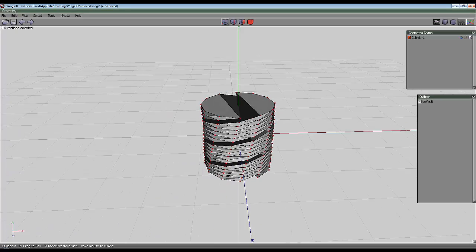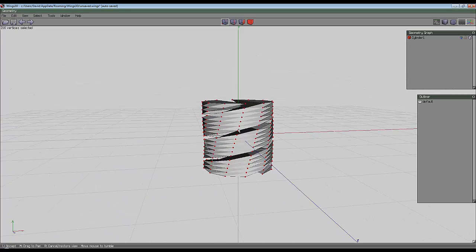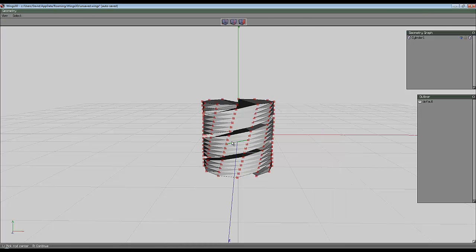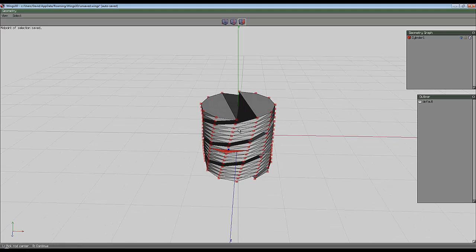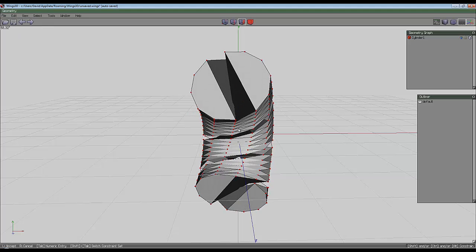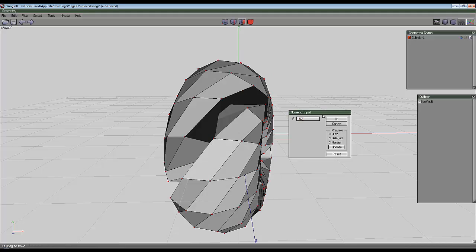Now the somewhat tricky bit is to bend this, so right click and bend. Select the face just to the left of one of the axes points there, so you can find it again, and then right click to confirm that selection. Now select the two top faces, so that highlights the end of the rod. Right click to confirm that selection, and then go back and highlight the face again that you started with. That gives a normal. Right click and then tab 180 degrees.